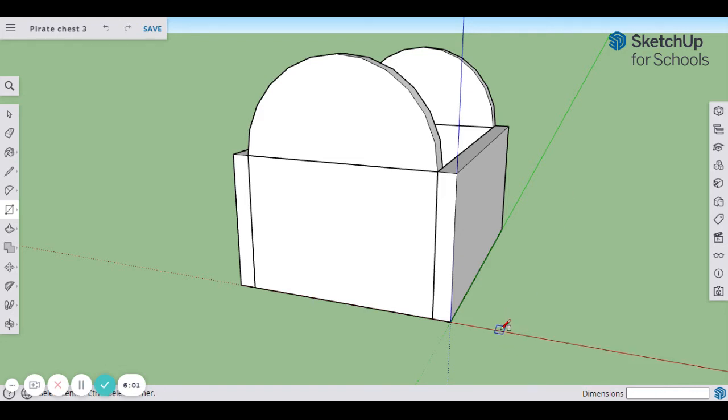Direction going. So yes, we could rotate it, but that just seems like it's going to be a pain. I'm not sure why, but sometimes with the rectangle tool, it kind of focuses from the center of the piece. There we go. So if that happens, just get a different tool, make something, delete it, and then it should be good to go again. So click, release, drag. I'm going to pay attention to the numbers down in the bottom right corner because I have this super long and skinny. The second measurement is going to be my length. So I'm going to go 5/8, comma, 10.5, and that should work better this time.